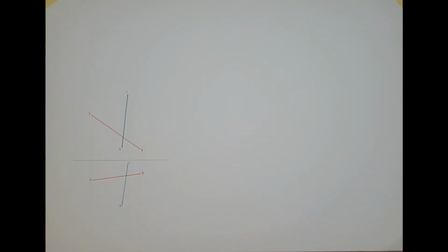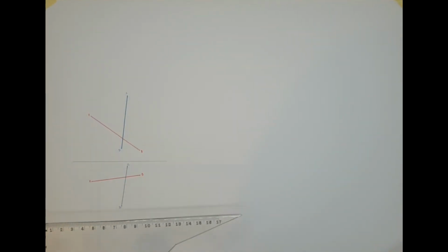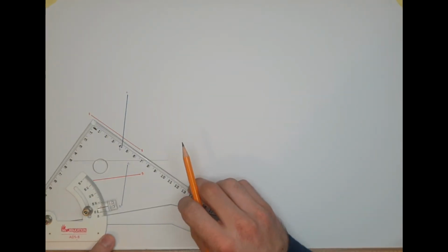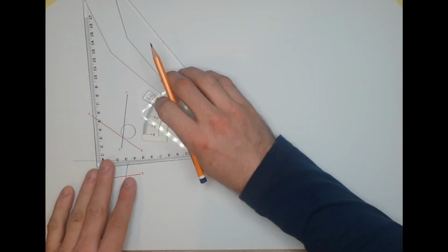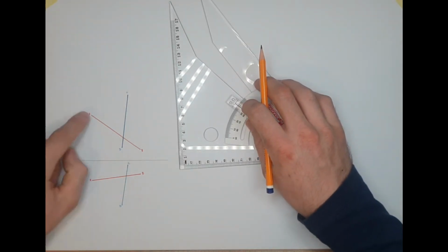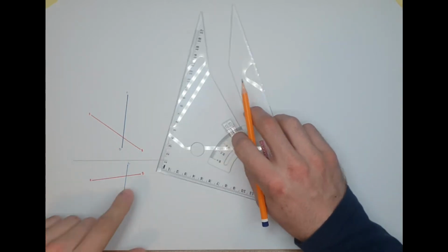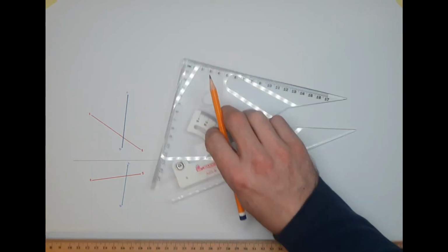If you want to draw this at home, I'll just give you a couple of general measurements for this anyway. The line AB, that red line here, sorry, is 70 mil long, and I pitched it off there at an angle of 35 degrees. Point A is approximately 55 mil off the ground. So 55 mil up, 35 degrees down, 70 mil long. Point D there, just pick the position for it, whatever you think yourself really. It doesn't have to be too exact here.